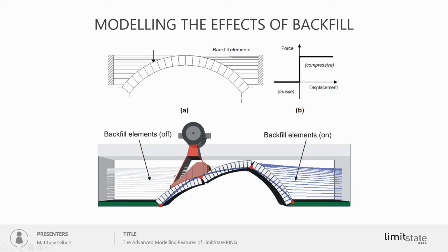Secondly, we have dispersion of whatever vehicle load we have on the bridge, so that by the time that load reaches the masonry, it's actually more spread out, which is normally beneficial. And then lastly, as we sway into the surrounding fill material, we have passive type restraint coming into play.